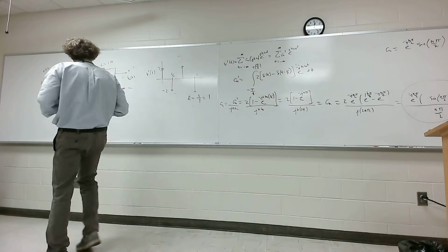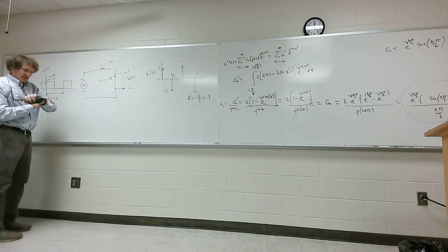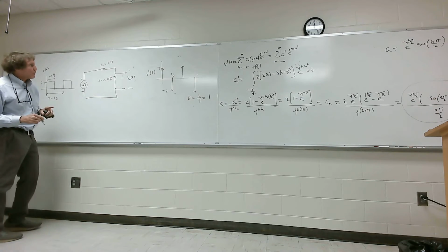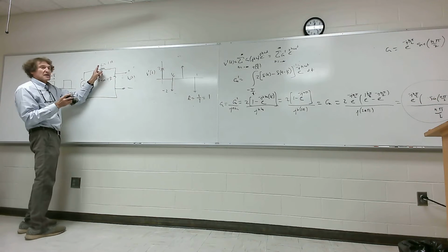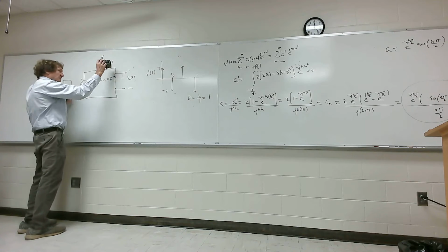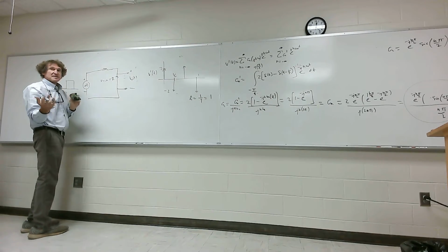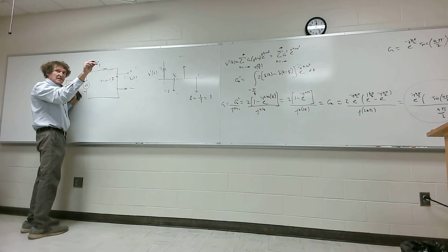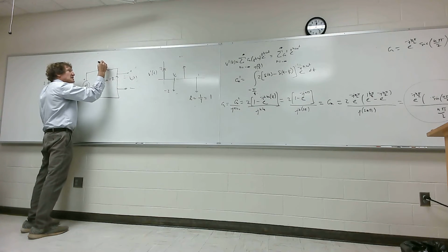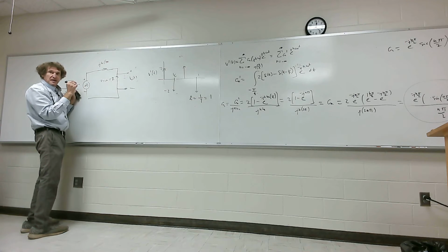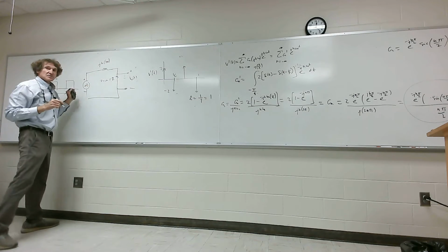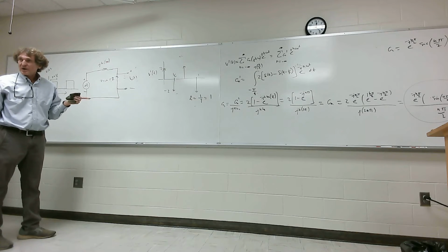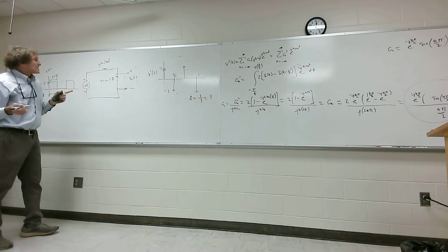Now that I've got that, I need my transfer function here, right? The transfer function would be v out over v in. So over here, what would it be? Actually, what do we do here? That's right. Now I put this as its impedance in the frequency domain. So it's going to be j omega naught n. Omega naught is just 2 pi, isn't it, class? 2 pi because the actual period is 1. So f naught is 1, and 2 pi times 1 is just 2 pi.